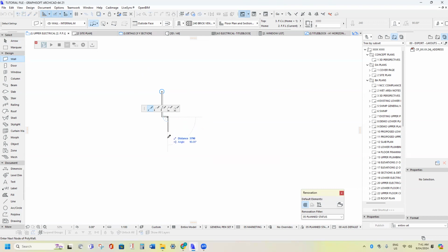So in this wall setting, it's all linked together. So I can do one angle and then change the wall to go this way, and it's all still connected. That's because up here I've chosen that option there, which as you can see, it goes right, then goes in, and then right. That means it's a continual wall. If at any point I double click, that's going to stop this continual wall, and then I have to re-click and start the wall again. There's also some other options for doing walls, which I'll show you later.